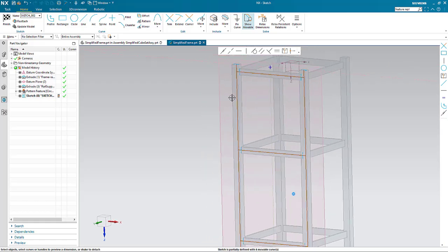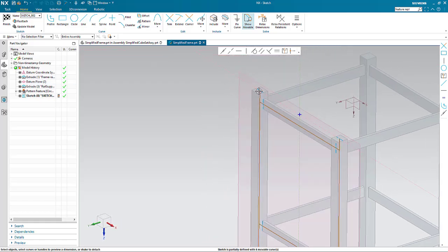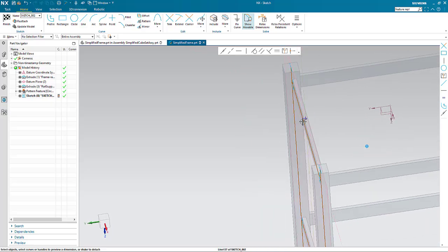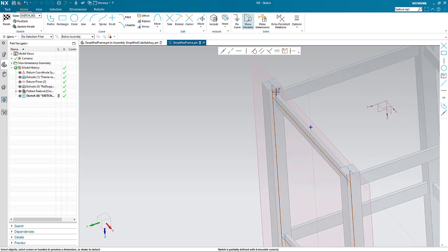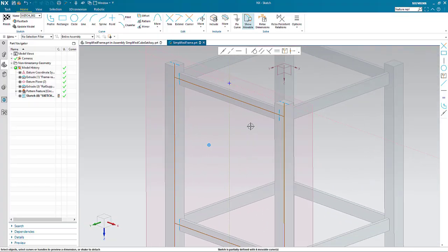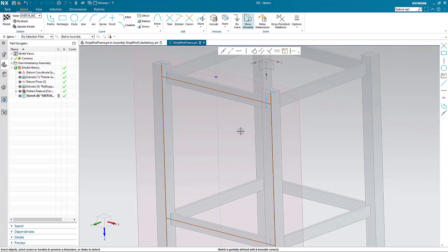Now, notice that I've chosen the center line of the rail, but I've not chosen the center line of these rail supports. So this is, I guess, an idealization that I'm making, that I'm not putting the thermal conductor through the center line of this component. I'm just going to make that sort of simplification here in the model.